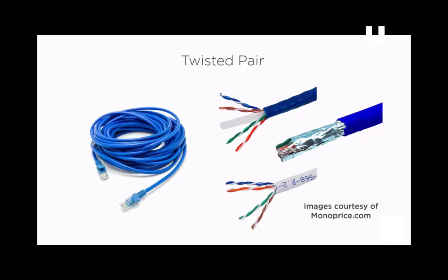Because when electricity passes through a wire, it introduces a magnetic field which interferes with our data passing through the wire. To overcome this problem we twist the wires, so that it cancels out the electromagnetic induction in the wire. This is the picture of the wire. As you can see, we have combined wires and splitting wires.